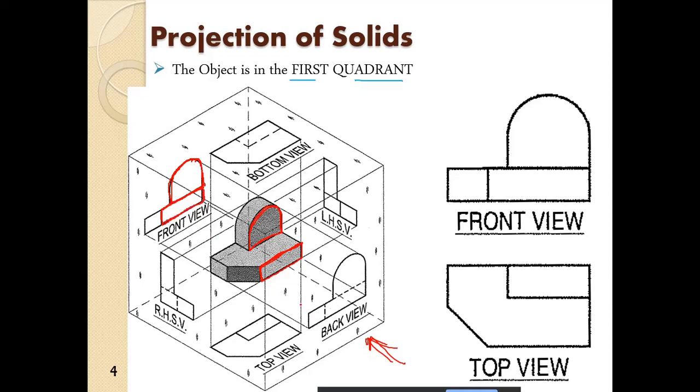Then when we see from the front, we will see this surface, but this surface is inclined in nature. So this point will be projected up to this point here, right? Parallel projections, so these lines have to be parallel, as we have seen for the inclined planes.